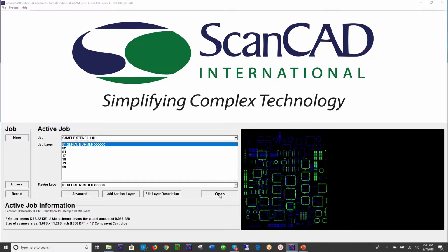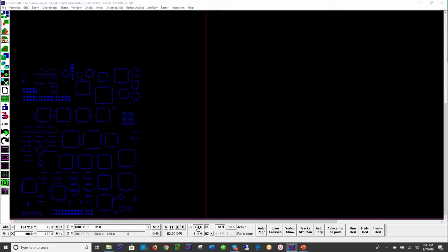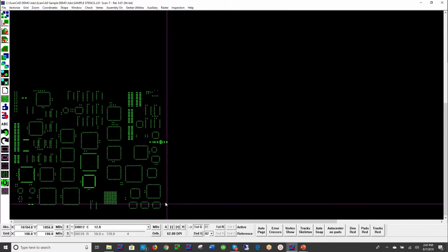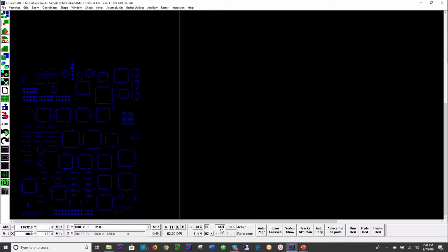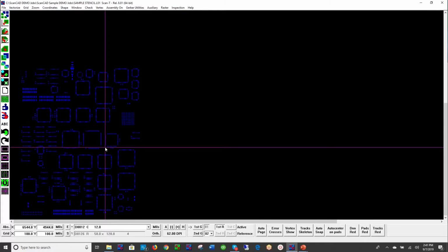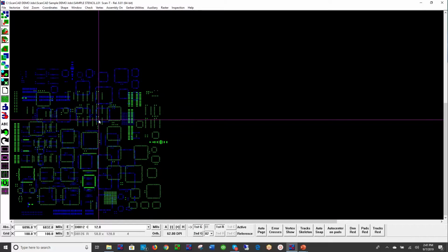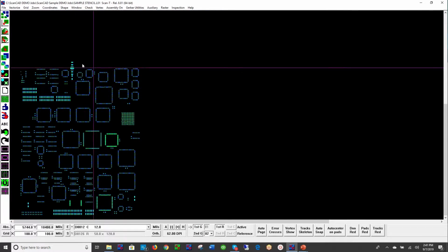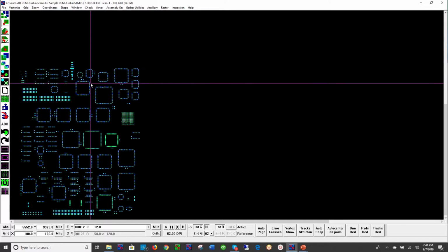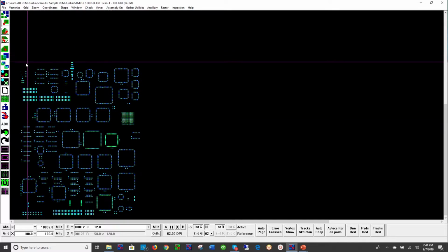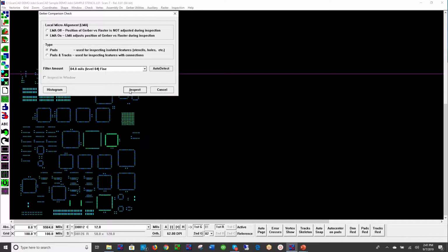And again, I'll show you more of the process now. The way the system works is you first import the CAD data in green. You next scan the part, in this case monochrome, using a backlight. And now we overlay. I just want to share with you, use these icons here, and this function here automatically flips and rotates to put the CAD data on top of the part. Okay? We are then able to perform an inspection.